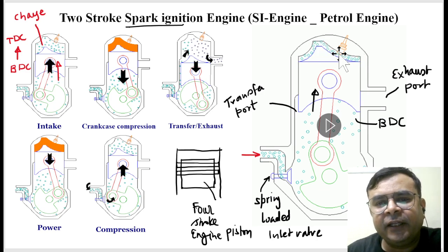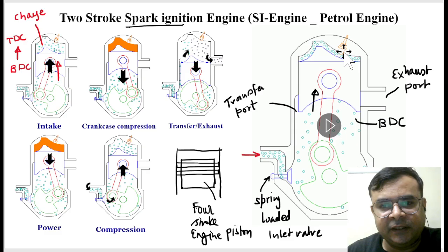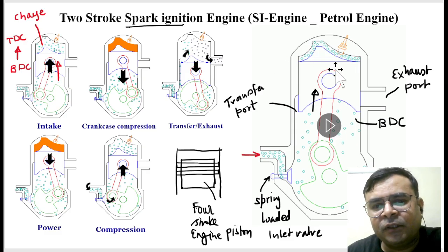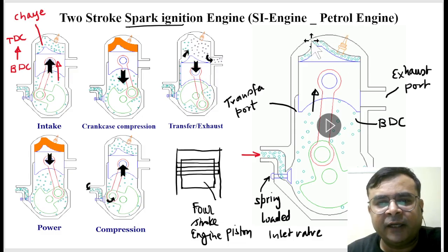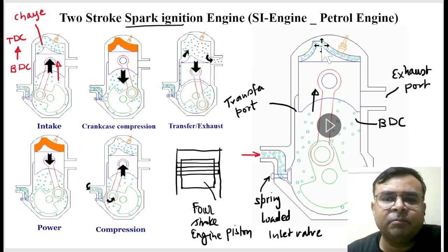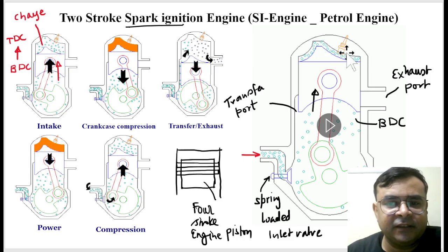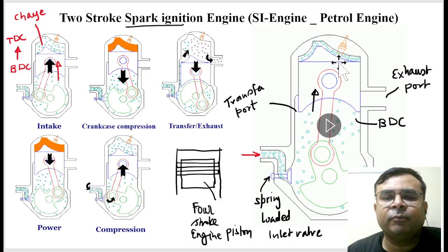Now it is ready to spark or ready to burn, is it right? So at this stage, when piston is located at the top dead center, with the help of this spark plug, you provide a spark so that this fuel gets burned, is that right? And because of this burning of the fuel, obviously huge pressure suddenly rises, and hence this piston moves.